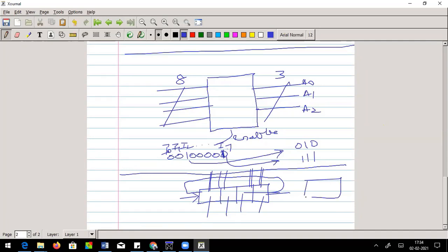Serial in, serial out is like, for every clock cycle you push this data, push this data, push this data, push this data, and move it out. Serial in, parallel out: after filling up all of this, within a single clock cycle you can put it in one register outside. So based upon your need, you can always shift, rotate or move data, 1 bit, 2 bits, any number of bits.